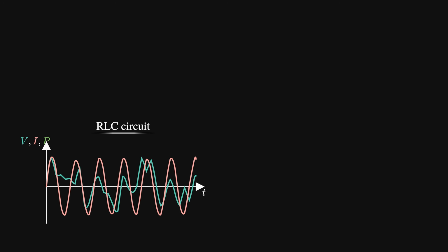This isn't very useful. However, if we add a capacitor and an inductor, the circuit behaves differently. Here is a current that could appear in an RLC circuit from the same antenna input. As you can see, it is a neat sine wave with one standout frequency. This has happened because in an RLC circuit, the current amplitude depends strongly on the frequency of the input signal. So, we see the current responds strongly to a small range of frequencies and weakly to others.